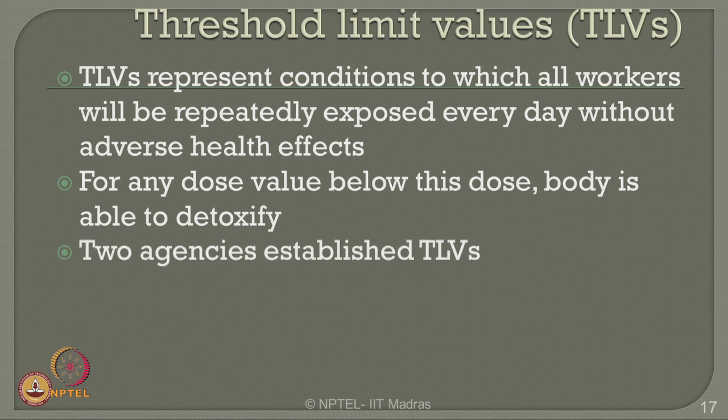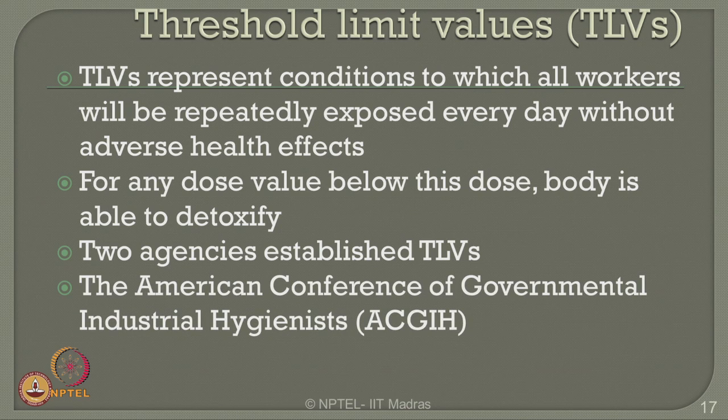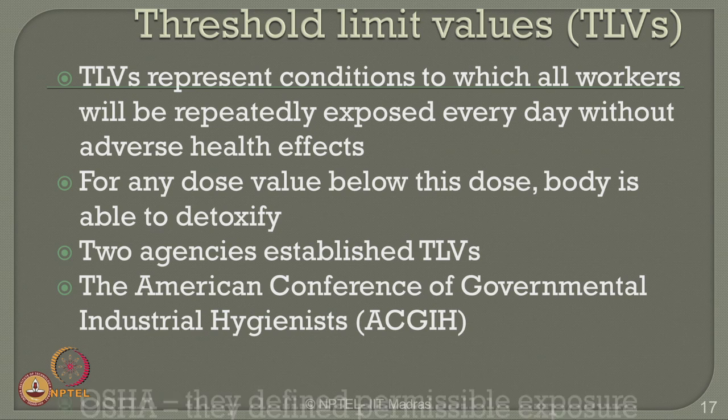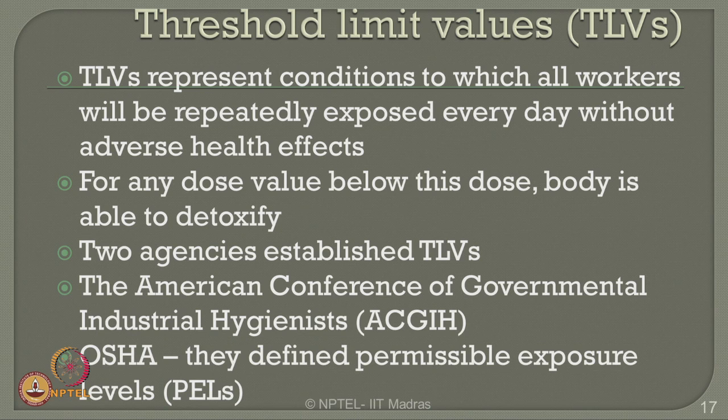Now the question comes, how do you estimate this? There are two agencies which can establish TLVs in the process industry. One agency is the American Conference of Governmental Industrial Hygienists, ACGIH. The other one is OSHA, as we defined earlier. OSHA of course gives the value in permissible exposure levels, briefly called PELs.